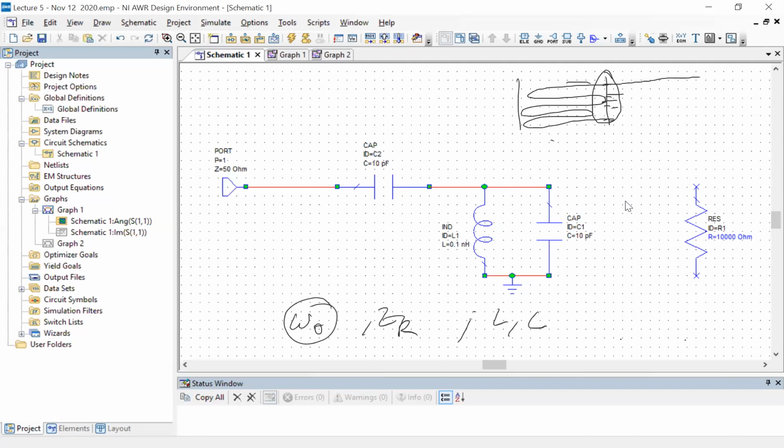Because that entire discussion was based on how to change Q factor. We are still basically discussing that only, right? Okay. This R is 50 ohms. This you cannot change. It comes from a circuit like this, without this coupling capacitor, this is fixed. So then the only options you have to change quality factor are these two quantities.